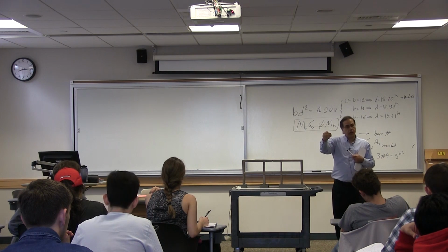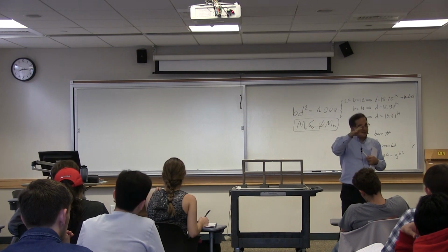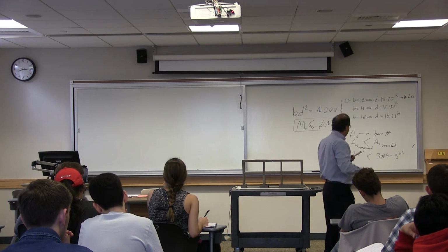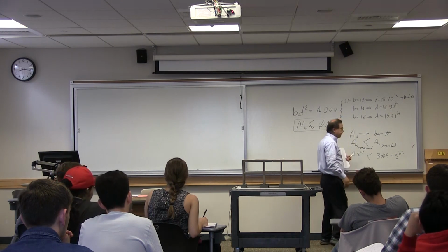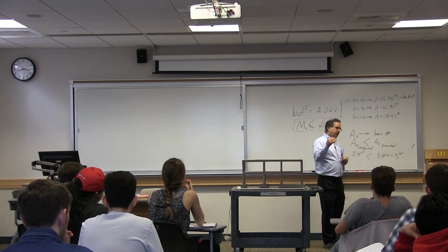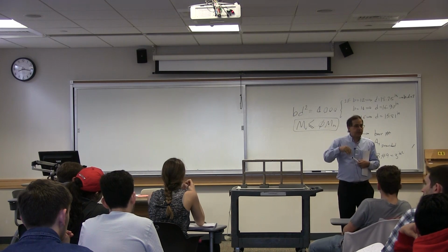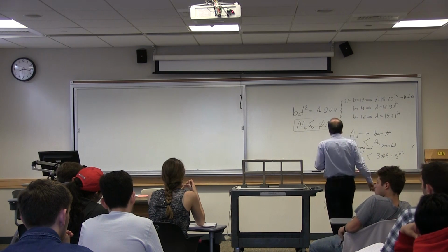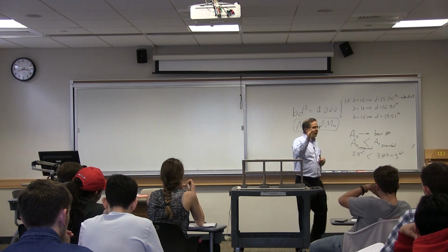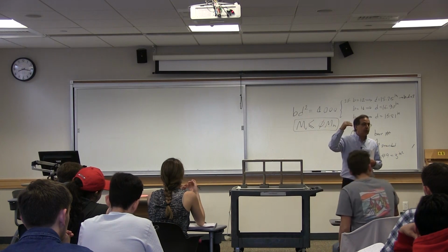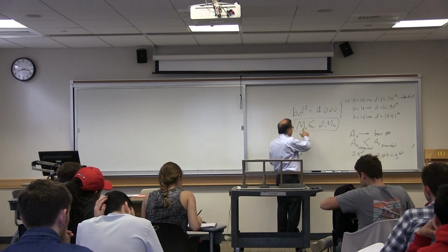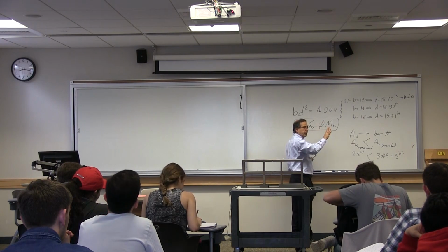You set them equal, and then when you make the decision at the end, you overestimate, you don't underestimate. You cannot say, I have 2.8, I provide 3 number 8 that is less than 2.8. As long as you choose more, then you are satisfying the requirement that Mu is less than or equal to phi Mn. There is no additional step needed. This is the requirement. What you start with, you set Mu equal phi Mn, equal, not less than or equal.